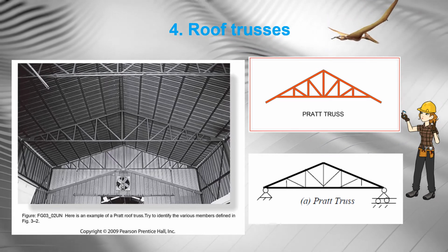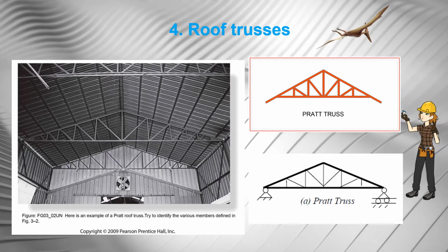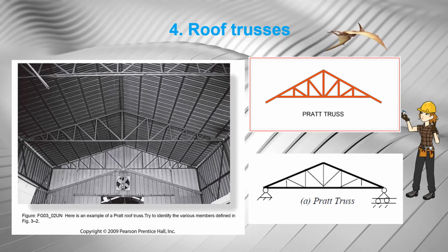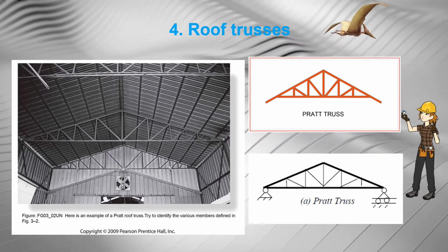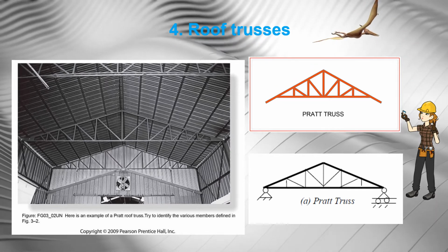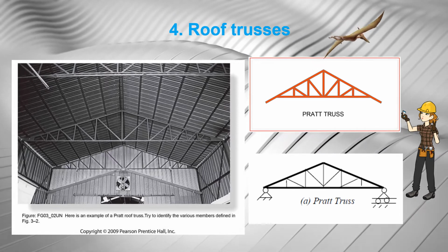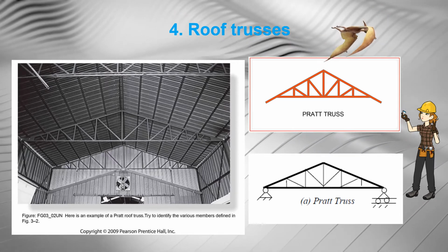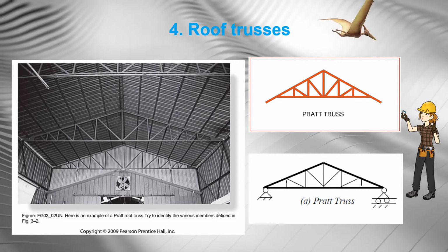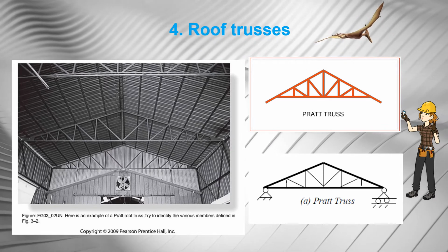Pitch roof trusses may have different configurations. Meanwhile, in Pratt trusses, web members are arranged in such a way that under gravity load, the longer diagonal members are under tension and the shorter vertical members experience compression. This allows for efficient design since the short members are under compression.